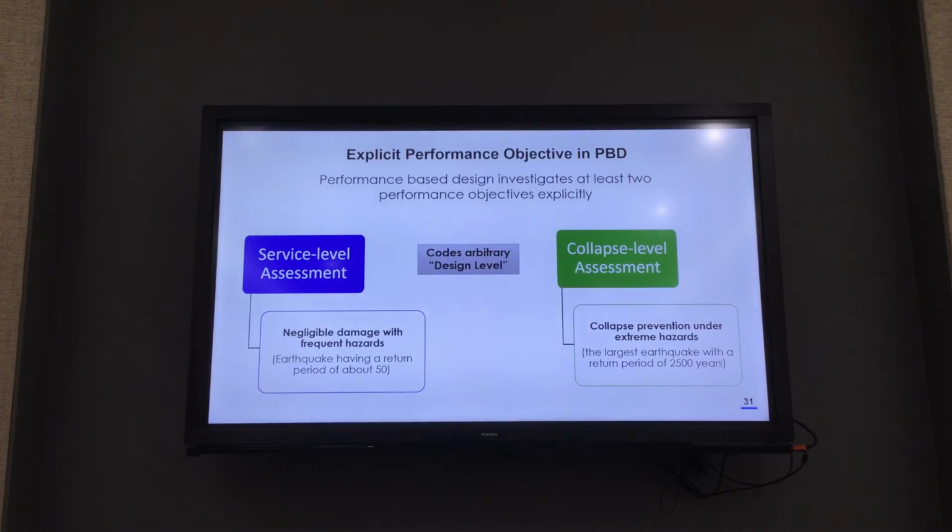As I mentioned to you, what is the live load typically for a university classroom? Nobody remembers. 60 PSF, okay, let's say 60 pounds per square foot, right? 30 kilograms per square foot, which is equal to about 300 kilograms per square meter, correct?